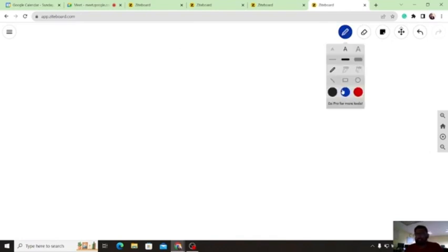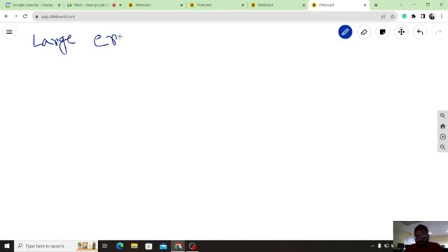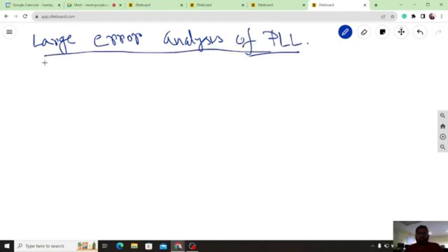So for this type of question, we have to do large scale error analysis of the PLL. If we want to do large scale error analysis of the PLL, the rate of change of the error with respect to time can be written in this format.